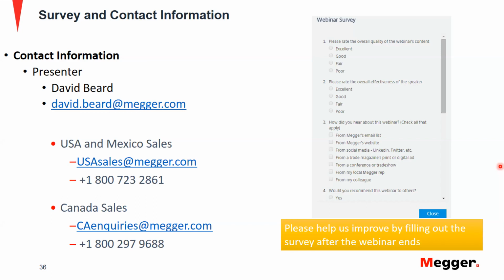Hey, Mike, before we proceed, I would like to point out another answer of mine, which I gave about the timing unit on the breakers. I see that Mariano is having an objection there. He is referring to using the primary current injection test set, which is absolutely correct. Definitely, primary injection test sets can be used to inject high currents on the primary breakers, and then you can measure the trip time using the primary injection test sets.